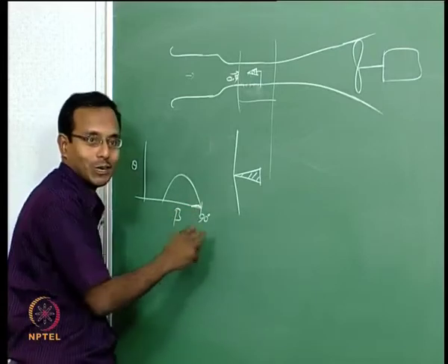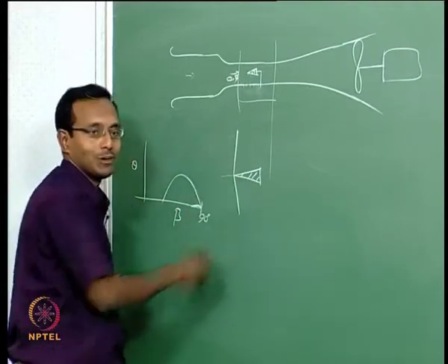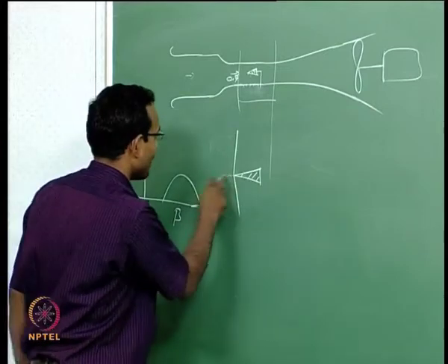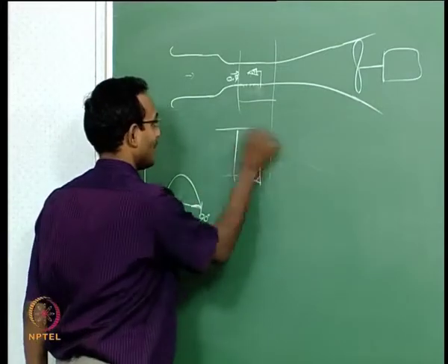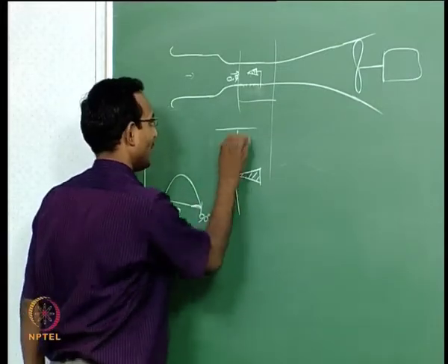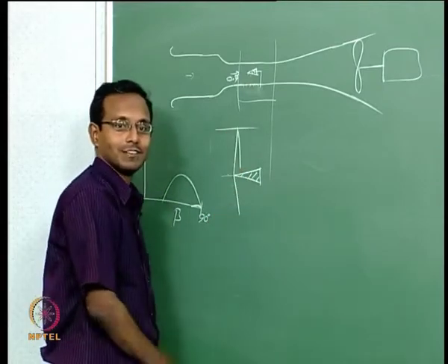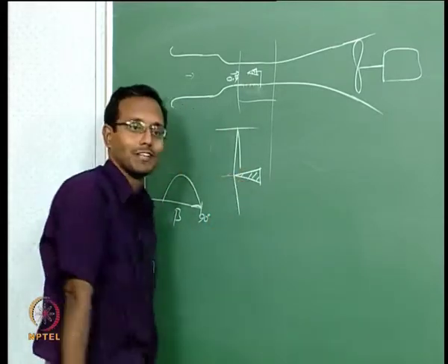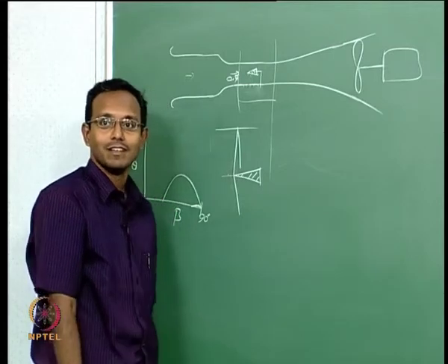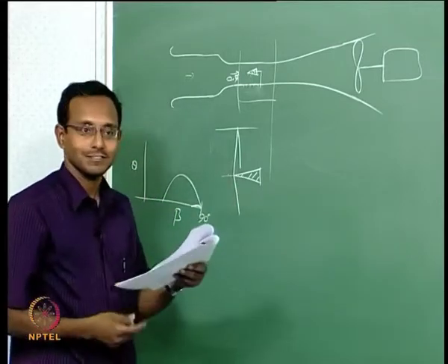Beta was almost close to 90, all the shock is almost a normal shock. Now what should be my model size for this? There is a wall here, the shock will go and hit back and come back straight. Now my model should be inside this itself, cannot be anything bigger. That could be a problem with this facility.